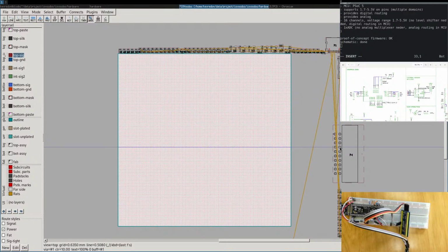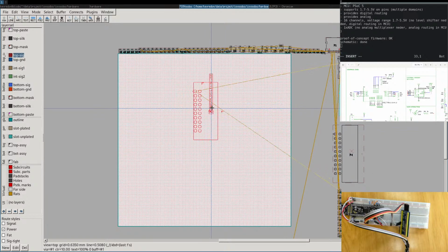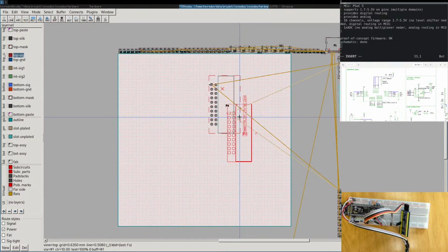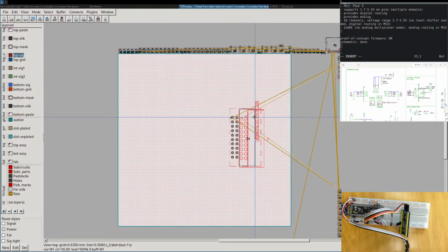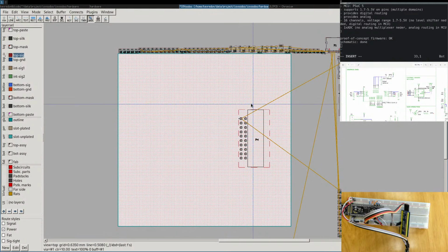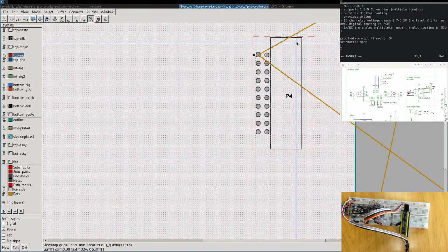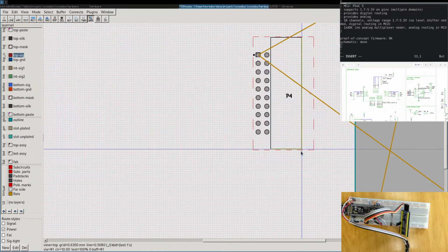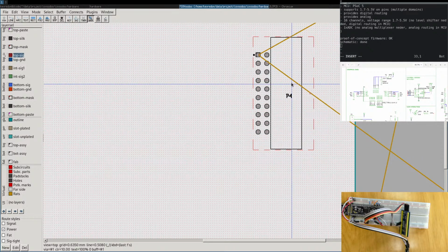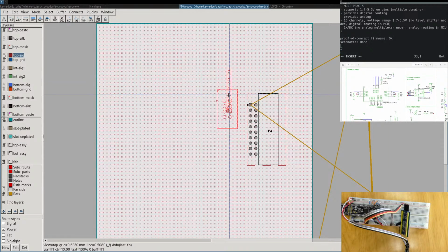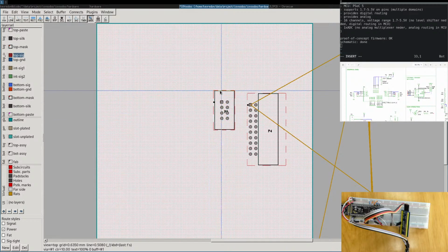So whenever you do board layout, you start with the placement, and then you do the routing. That's kind of important. We put it in the middle so we can have space. That's on the right side. That's a connector for connecting the outside, so the board will finish right here, so we can solder the connector on here. Although we could have the board going up to here, so we have a bit more trench under the connector. This is huge. It could be smaller, and actually it will be smaller.